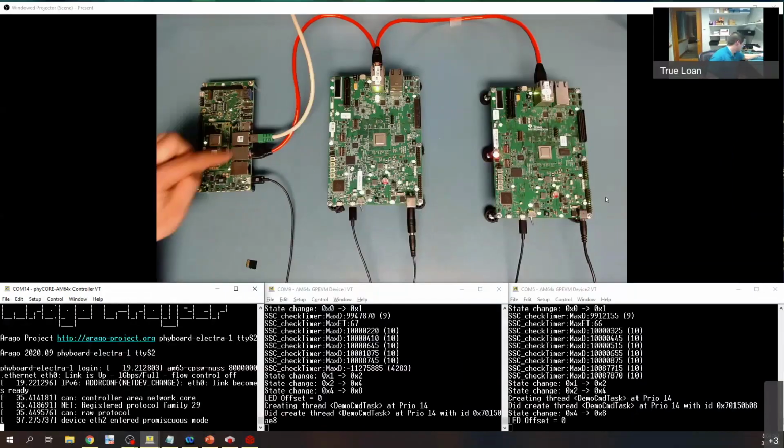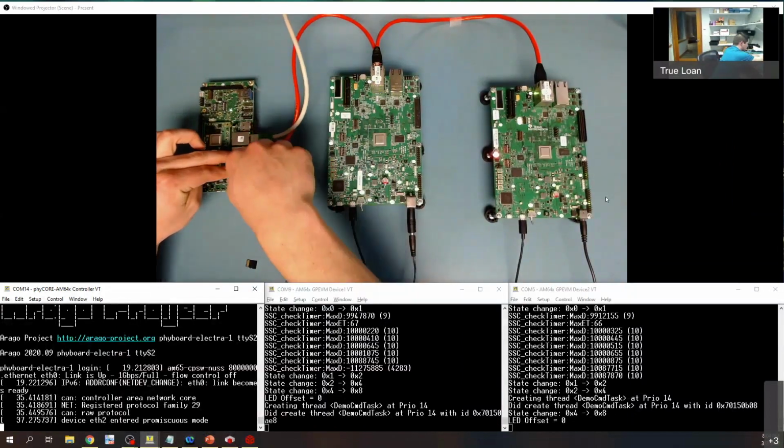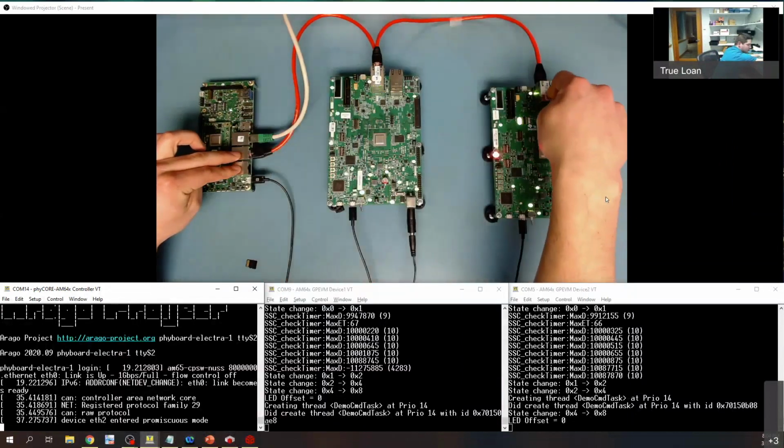So in this case here on the development kit, I'm actually utilizing one CPSW Ethernet port connecting the master to my local area network. And then for the actual industrial Ethernet network, I'm utilizing a PRU Ethernet. I can actually go ahead and show that again, just to point out on the physical hardware what that looks like. So this is the CPSW Ethernet, and this is connected to my local area network. These are PRU Ethernets. I'm actually utilizing them to communicate with my slave devices.